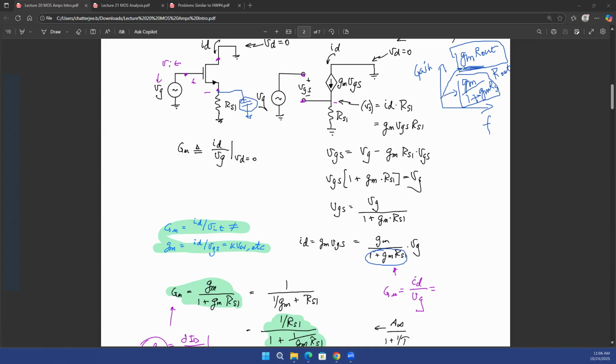And in between, when the frequency changes, between the 2 points where the capacitor is considered as an open and where the capacitor is considered as a short, you will have gain which is in between those 2 extreme points. So this looks like a high pass filter, right? That basically says the effect of this capacitance is a high pass filter.